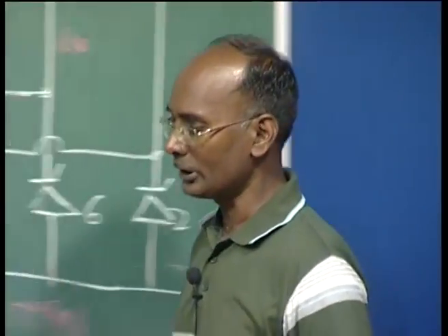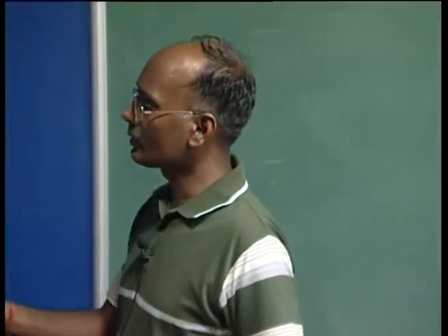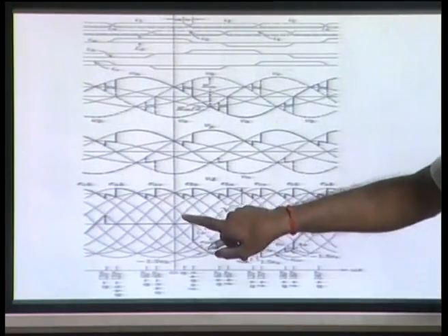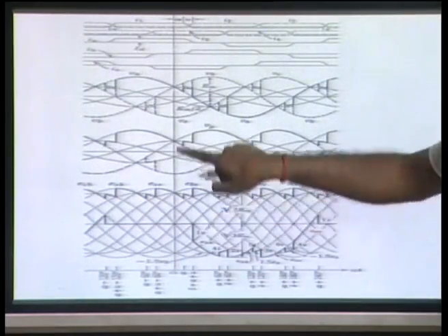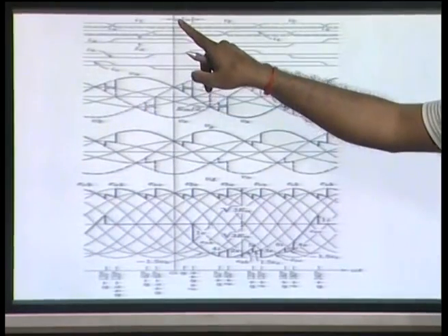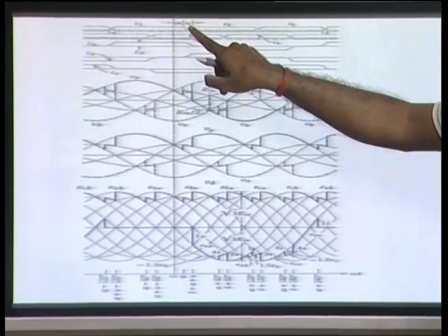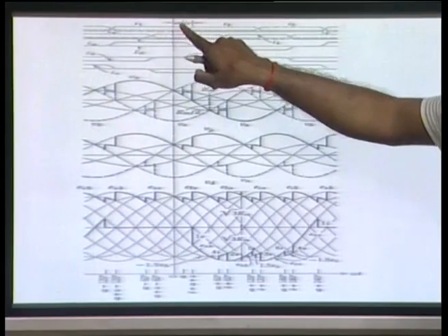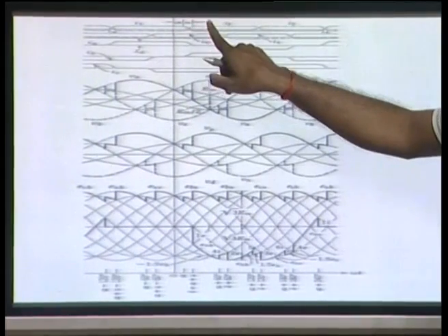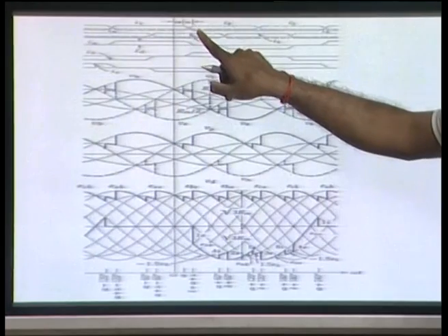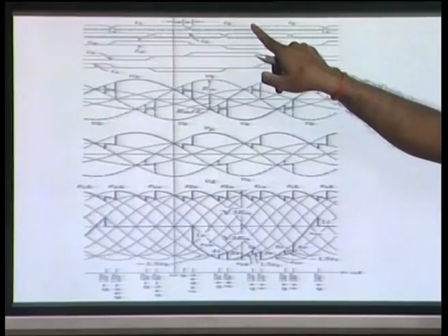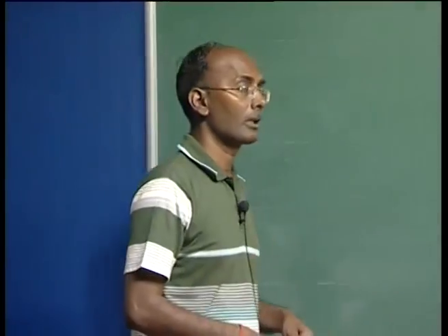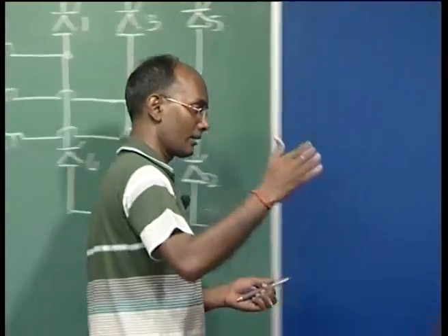Similarly, you can see the current changeover here. This is your axis, because the commutation voltage we have taken for this one is EBA. So, this is the axis here, also omega t. Now, I3 was there up to u, and then I1 is here, because alpha is when we give the pulse to 3. So, I1 was Id. Now, there is a commutation between 1 and 3 taking place. Here the current of I1 is decreasing and I3 is picking up, and again it goes on. This is the upper limb current and the lower one is the lower limb current. So, it is basically taking care of all the things. So, this is the current.